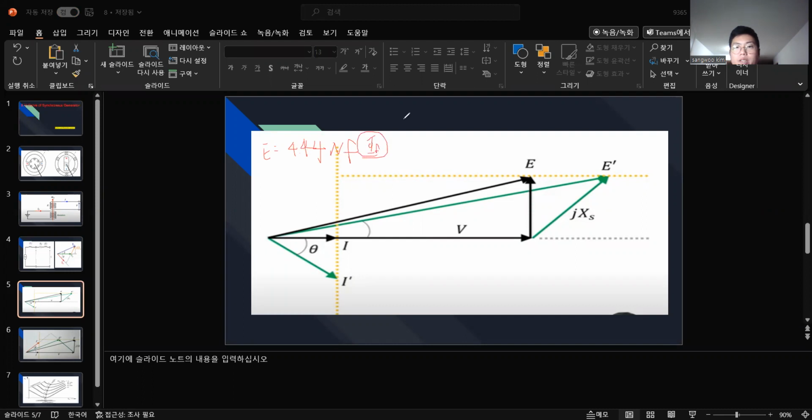So this part, I said, is controlled by the IF, the excitation part, right? So today we will learn first about overexcited and then underexcited. Overexcited means it gives you more, like being more of a supplier, to supply more power, reactive power, right?